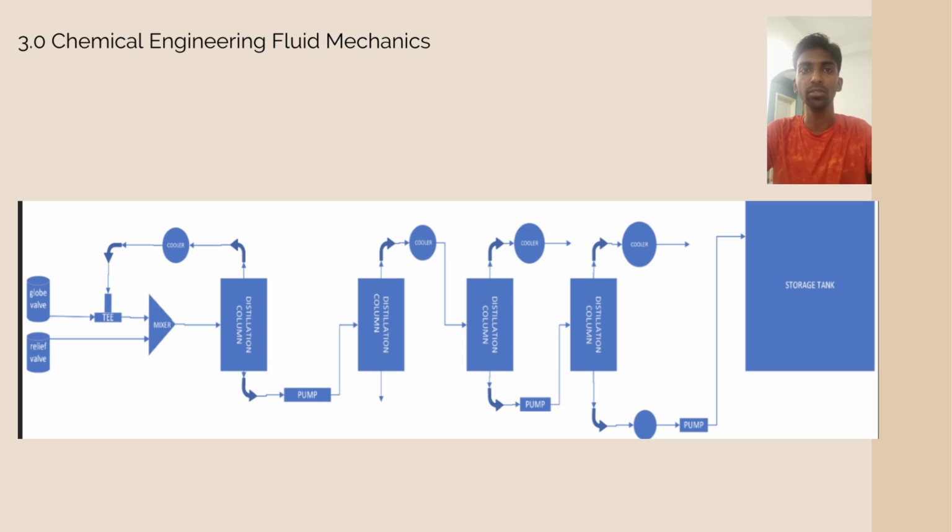The picture shown above is the piping layout of the system. The two valves in the feed control the amount of oxygen gas and acetaldehyde fed in. The pumps shown under the distillation columns 1, 3 and 4 ensure that the fluids reach their predestined places. The bent arrows indicate the 90-degree standard elbows, and there is a standard T present at the feed.